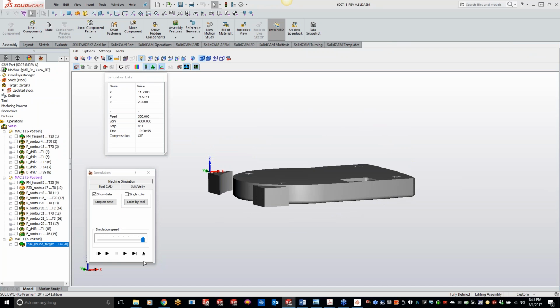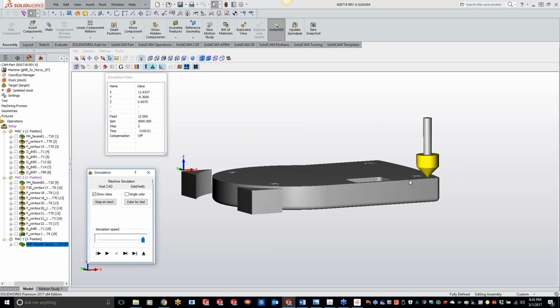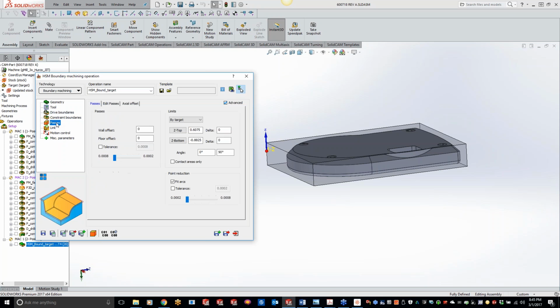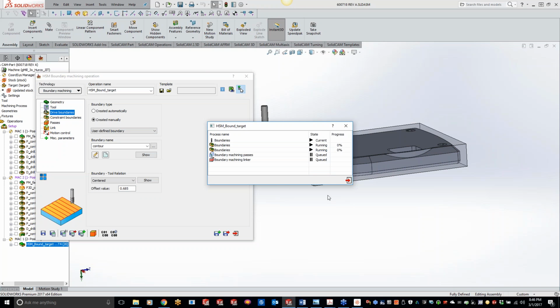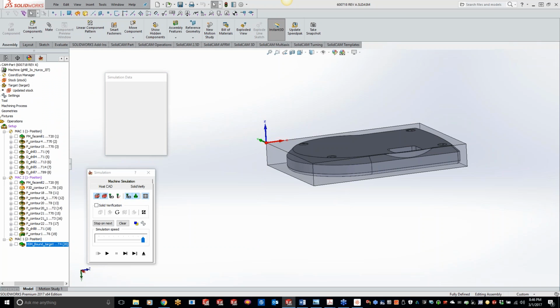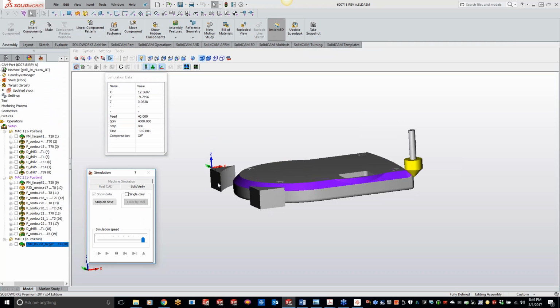Yeah, so we're kind of up, and just the tip is just barely touching right there. So for this particular one, what we would have to do, George, is come into our passes and put a negative wall offset of what that value is there. So that's why I kind of left it on my drive as centered, and then I just did the 685, or basically half the cutter, a little bit more. And now everything should stay the same. Yep.